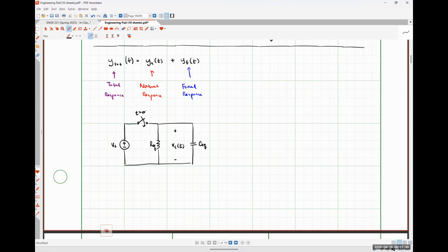Okay, so that's all the forced response is. So we can essentially just say that our forced response is really just y at infinity, or what our signal settles to after we wait a long time for the transient to decay. Okay, and that will only be non-zero when there are sources present in our system that are making it not zero. Okay.